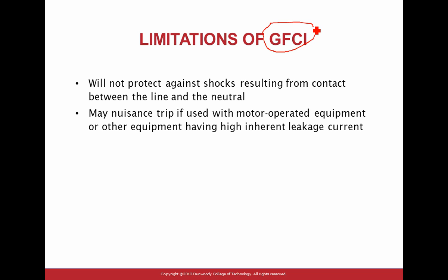It will have 5 amps going in, 5 amps going out, no problem. So, nuisance tripping on some equipment, that's why we don't use them in a chemical process or what not. Labs exclude them because they could nuisance trip and interrupt the process.